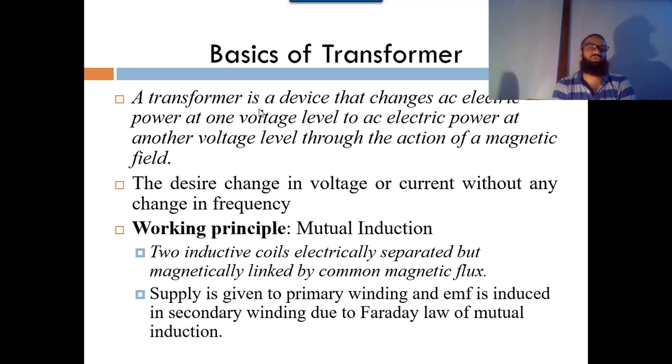One thing you should know is that the input power and the output power of the transformer are the same, so it is not an amplification device. It works based on the mutual induction phenomenon, where the magnetic flux in the primary side is induced in the secondary side, and the output voltage depends on the number of turns of the secondary side. So it is a physical application of Faraday's law.